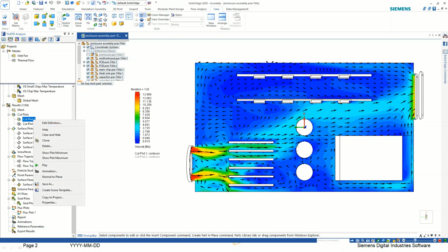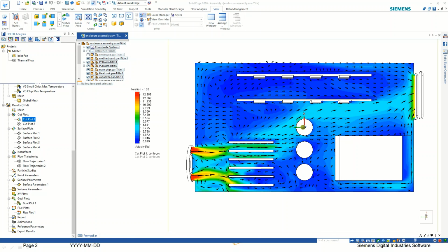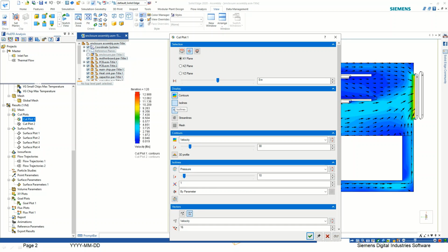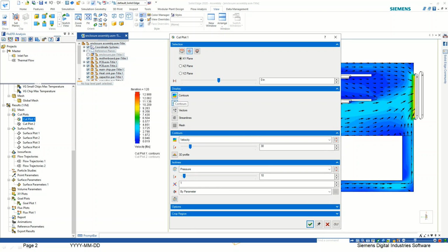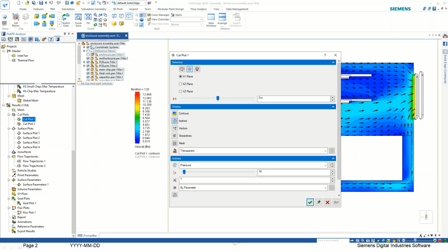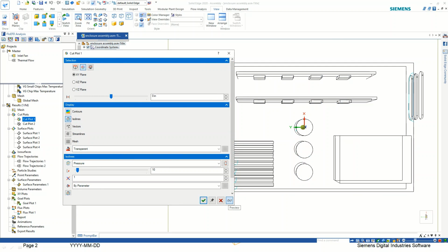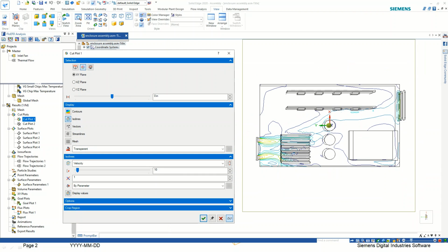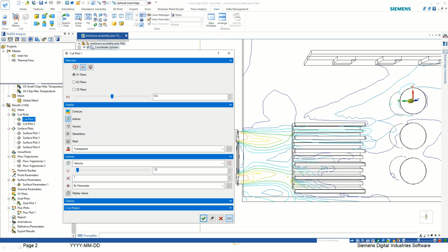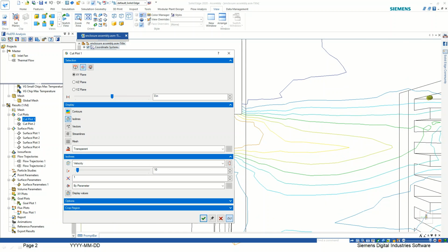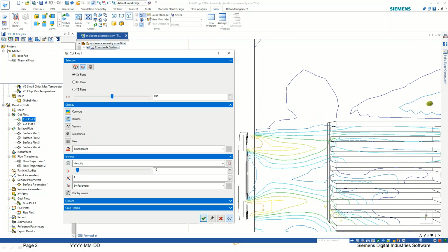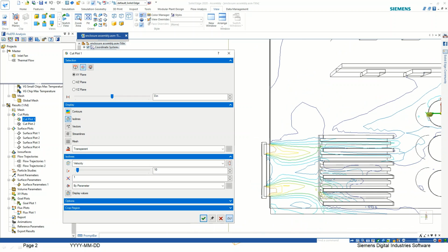We have this option called velocity contour. So we have multiple things like this. We have isolines. We can apply isolines so that we can figure out the values of similar range. So I'm going to apply it, suppose velocity of similar range. You'll get the idea that the lines with yellow will have similar velocity, the green line will have similar velocity, and what the velocity is, you will get the idea from here.